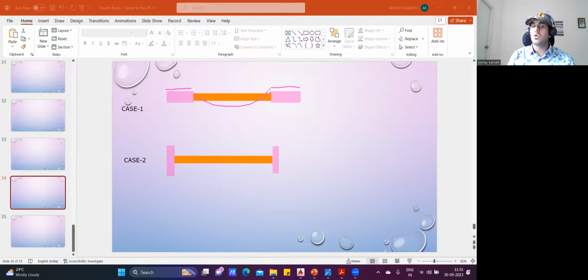More bending of the beam will not happen because the longer depth of the column you have placed is parallel to this direction. Got it? Whereas here, when the load comes on the beam and it tries to bend, you have only this much depth to resist that bending. The majority of your depth is going down, which is of no use. So only a small depth. You see, this is capital D.